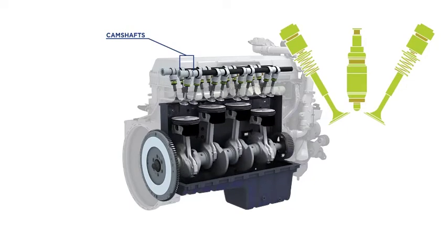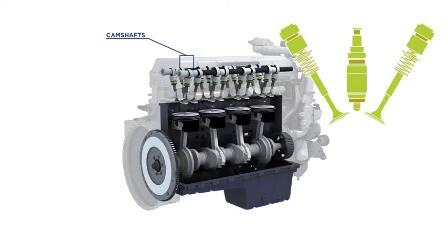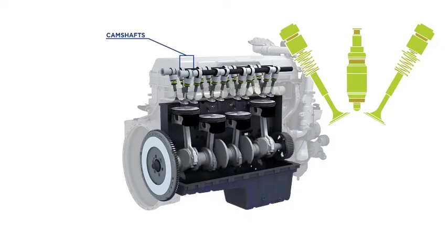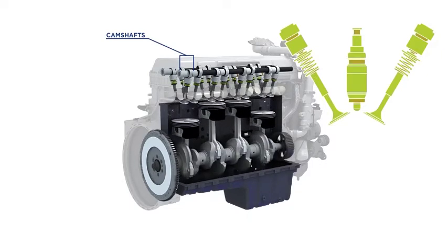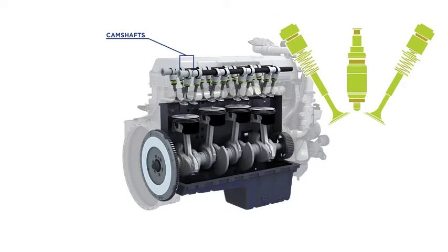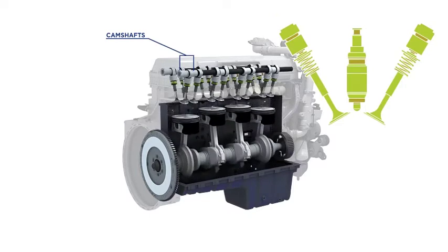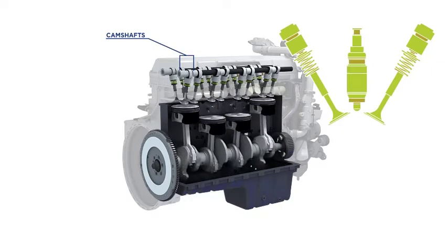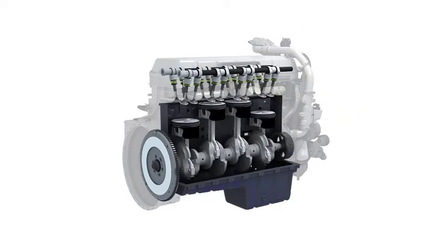Several valve train components, such as cam lobes, cam followers, push rods, rocker shafts, and valve stems, have metal-to-metal contact as the engine turns. To prevent wear on these surfaces, the engine oil must have effective anti-wear capability.